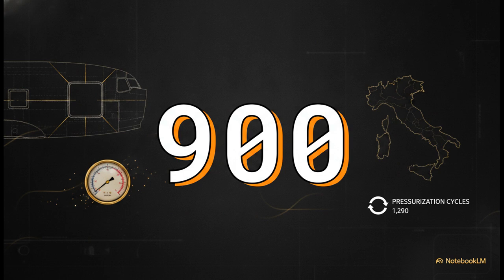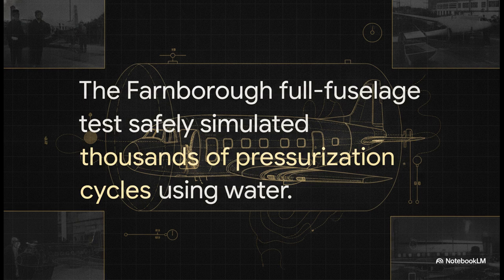To solve the mystery behind these incredibly low cycle failures, investigators at Farnborough, England came up with a genuinely brilliant test. They took an entire, fully intact Comet fuselage and placed it inside a massive custom-built water tank. By filling the inside and outside of the plane with water and then pumping additional water into the cabin, they could safely simulate the pressurization cycles of flight.